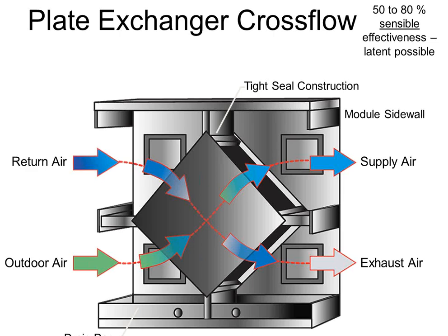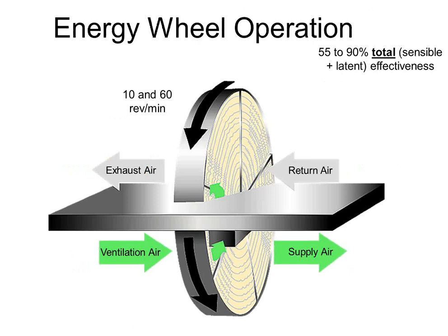If you want, you can take 2 glasses of water and set them on your desk, put food coloring in one and not in the other, and then put a piece of string between the two. Eventually the vapor pressure will wick the moisture up the string and into the other glass. And instead of 1 dark blue glass and 1 clear one, you'll have 2 light blue ones. Same basic principle applies here. We wick the moisture through to pre-humidify or dehumidify the air depending on the season.